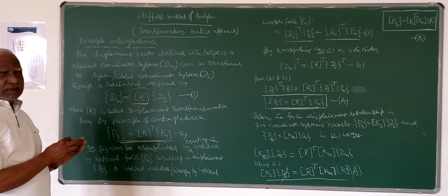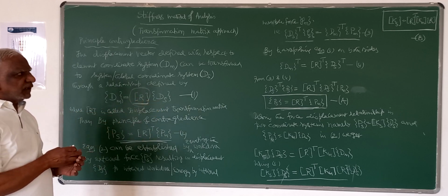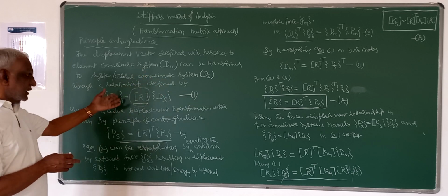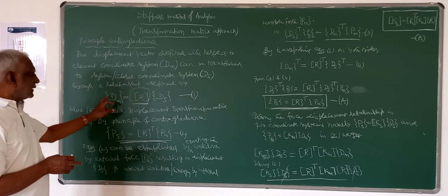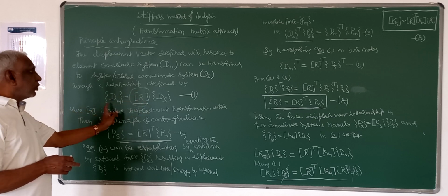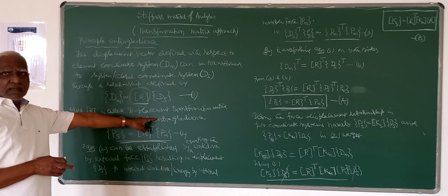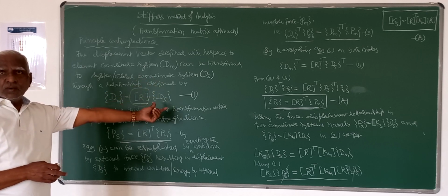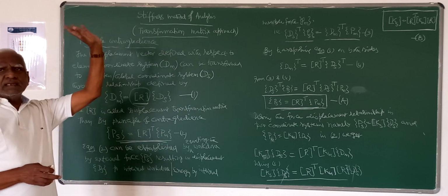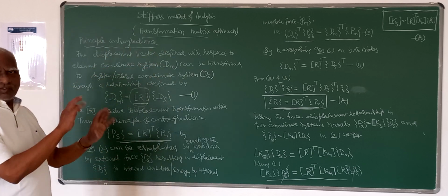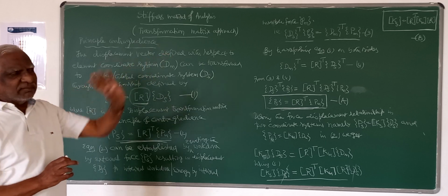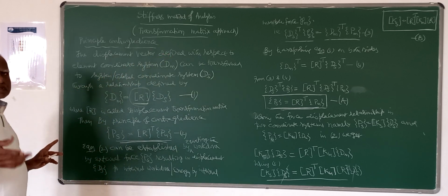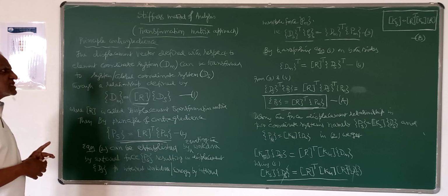This you have to remember. Of course there is nothing new here. The same thing I developed in the flexibility method also. Same principle of contragradients, but there I used the force displacement transformation matrix. That is, I used Pm is equal to T into Ps, and I developed a similar type of flexibility matrix relationship there, which I used completely in the analysis of beams, which you have already seen.